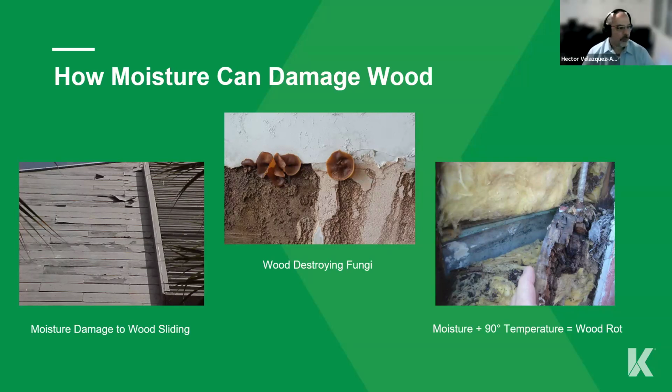Part of the things that we're seeing now, more and more, that we're getting involved in, are lining our pipes on our wet stacks, especially on taller buildings. Most of our buildings in Florida, or some of the buildings in Florida, are already reaching 30, 40 years. Some are close to the coastline, especially when you get a lot of people coming in and rinsing off all the salt and everything from the ocean, you start getting damage to the cast iron pipes, how they were installed originally. So now you're getting a lot of issues of water intrusion coming in because of piping failing,